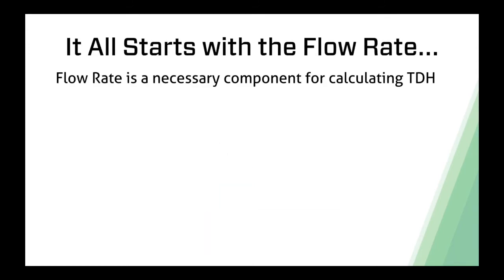As I mentioned, it all starts with the flow rate. The flow rate is essential to start with because calculating total dynamic head depends on the flow rate. If the flow rate changes, the total dynamic head will change as a result. So the general steps are this.